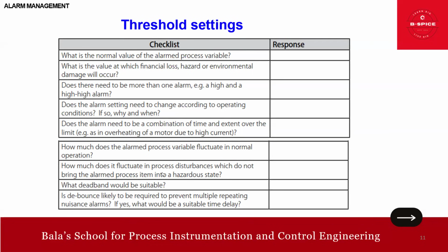What deadband would be suitable? Is debounce likely to be required to prevent multiple repeating nuisance alarms? If yes, what would be a suitable time delay?